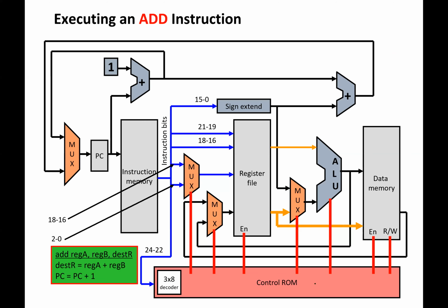And so we saw that for the add instruction example. We went through all the instructions, what we set the control ROM to. So go back, look through those if you want any more clarification, but I'll quickly redo the add instruction so we're up to speed. If I'm figuring out how to control each of these red lines coming up, this is controlling how data is moving through the data path and what operations we're doing. Well, the ALU, we defined such that a 0 going into the control input will do an addition, a 1 will do a NOR operation. So that's obviously going to have to be 0 to do that add.